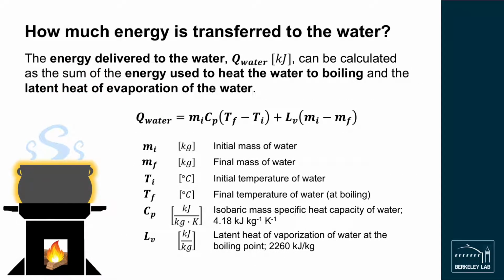In order to determine how much energy was transferred to the pot, the temperature of the water should be monitored with a sensor of accuracy and precision of at least 0.5 degrees Celsius over the expected operating range. We recommend using K-type thermocouples with a high-quality reader. While thermocouples tend to be less accurate than resistive sensors, they are significantly more durable. Regardless of the type of sensor, it should have a probe suitable for immersion in water.